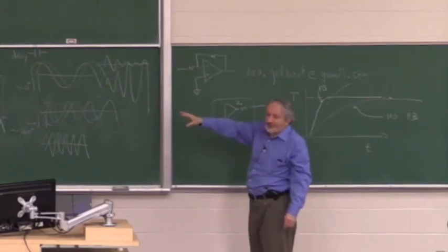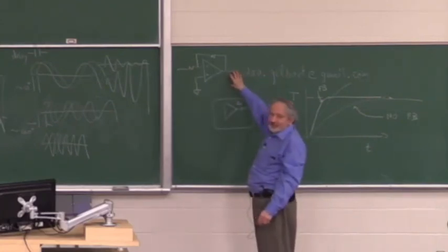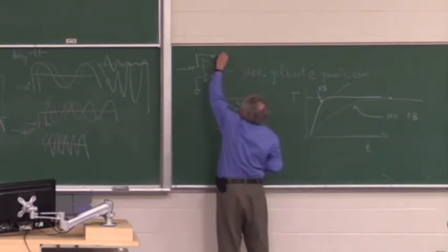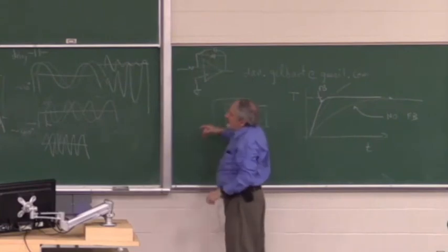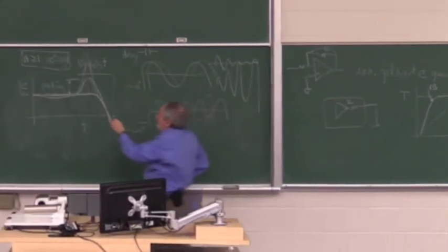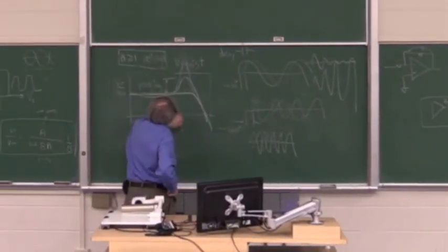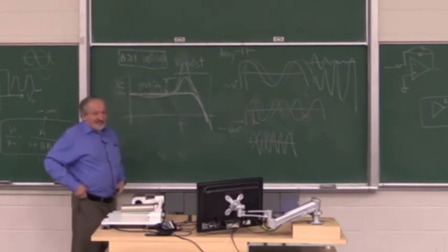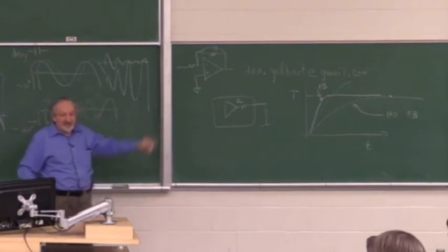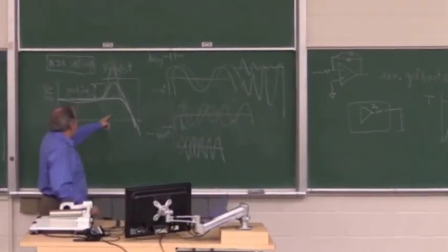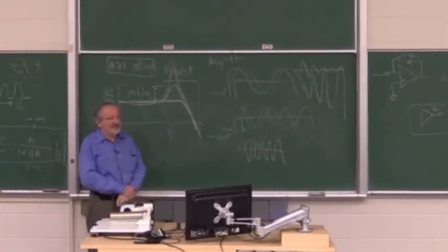Sometimes op-amps become unstable because of capacitive loading, like a cable capacitance. So when it becomes unstable, the typical solution is this. What this does, it makes the open loop go down faster, right? Because it increases the negative feedback for high frequencies. So because of that, it cannot oscillate because it runs out of gain.